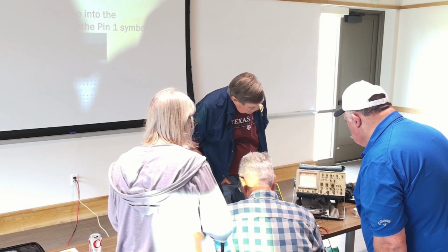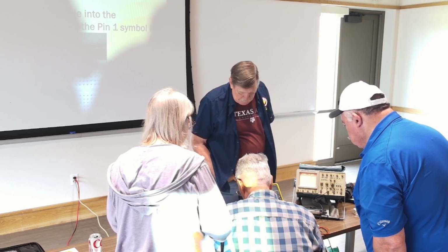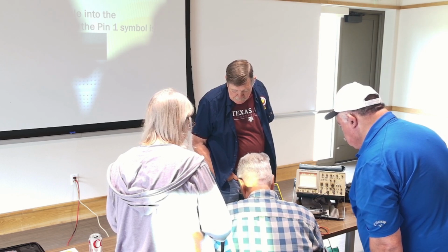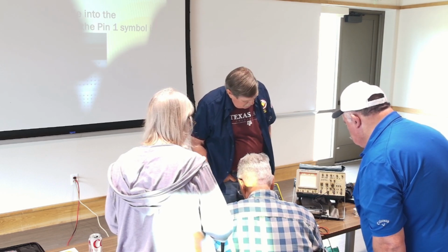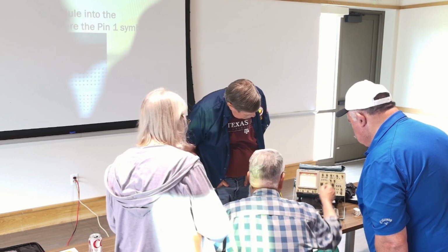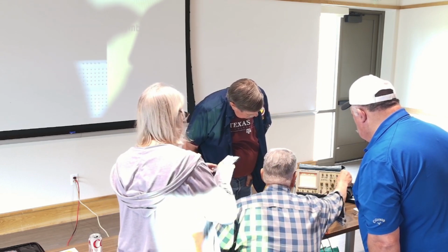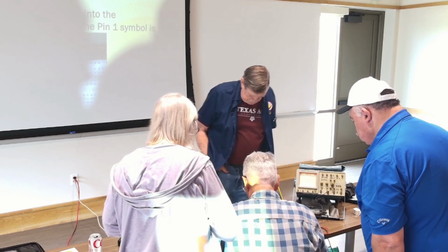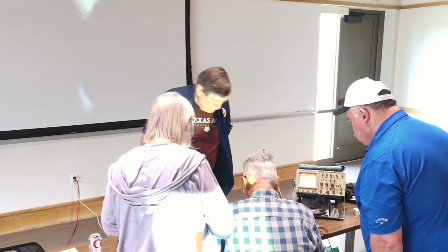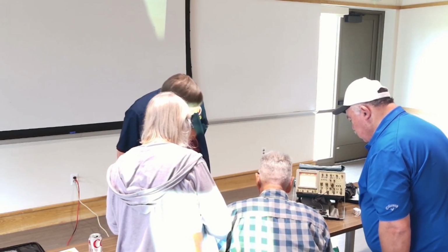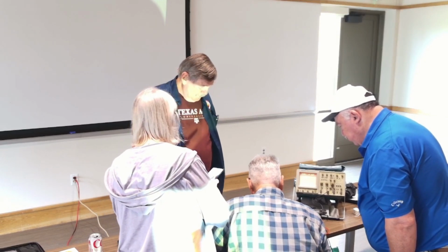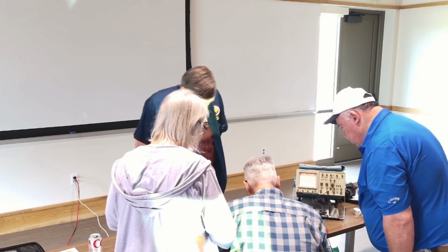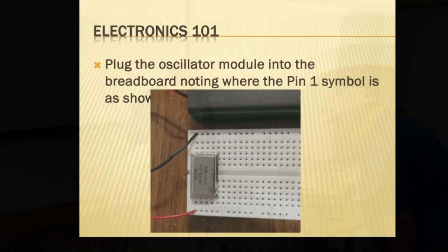This little ringing thing that's there, 3.9996 megahertz. There it is. Pretty close. I'll give you an A+ for that. Okay, that's how it works. I gotta take a picture of your working. So that's the idea. Now, we could probably tune the probe and get rid of some of this ringing and get a better picture. But more than likely, the actual circuit is doing some of that ringing itself. It needs to be filtered.